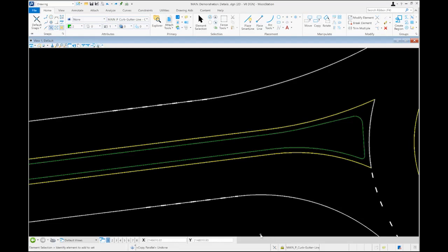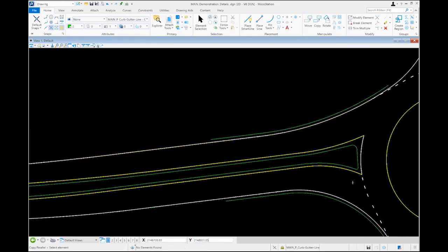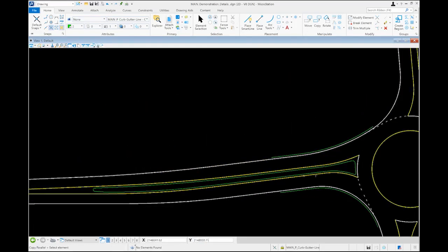Type 2 curb and gutter is typically used along the outside curb line, which has a 2-foot gutter pan. So we'll go through and lay in a 2-foot offset from our edge of pavement through our entry and exit curves to establish that 2-foot offset. Now, note that the length of the curb line along the outside does not need to necessarily match the length of the splitter island.